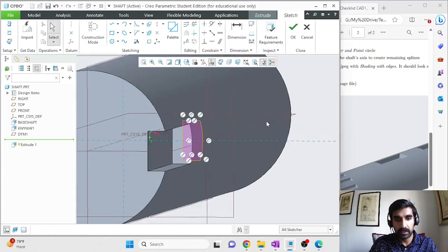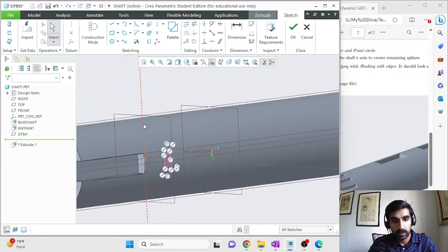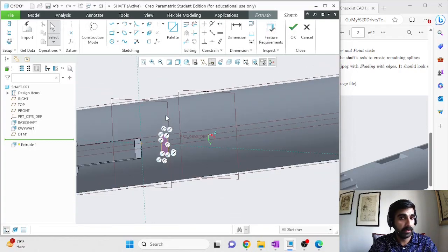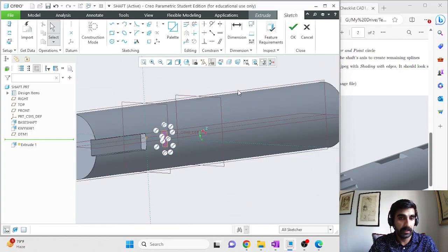So now if you look at the sketching plane where you're working, sketches have been created along these lines which have been projected from the edges that you selected which were on a different plane. So that's a very convenient way of using projections of existing features on the plane where you're working to create sketches. So what we have over here is this cross section sketched onto this new plane that we made. I'm happy with this cross section.